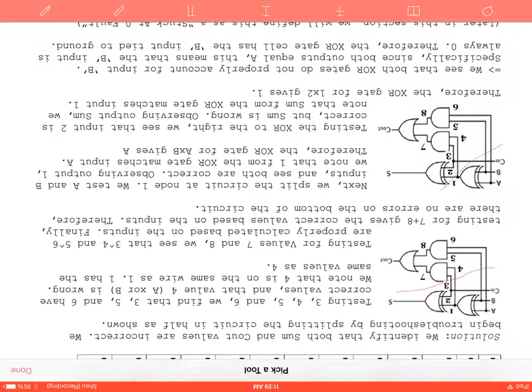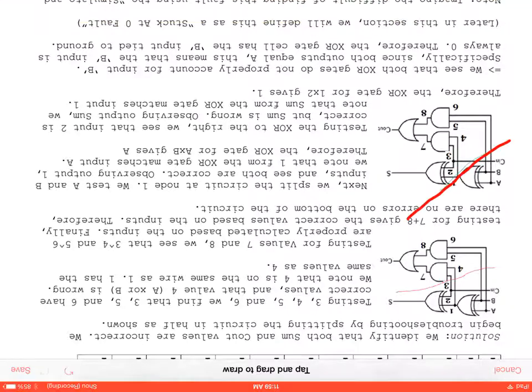So here's the thing, though. By using the method, we've split the circuit, and we know that we have a stuck at 0 fault here. This is where people waste tons of time. Right here, this next step is where you're going to save yourself hours. Because here's what will happen. You found the error. You fixed the XOR gate. But it doesn't solve all your problems. Because you're still going to have wrong values on the sum.